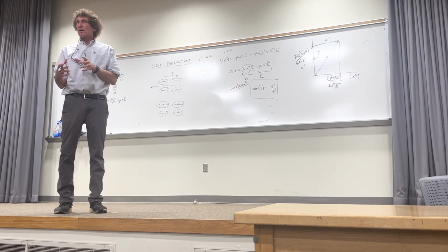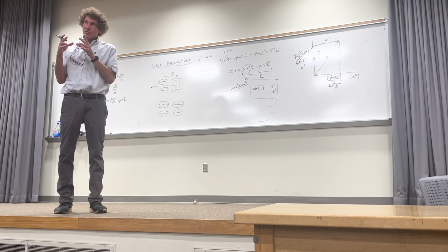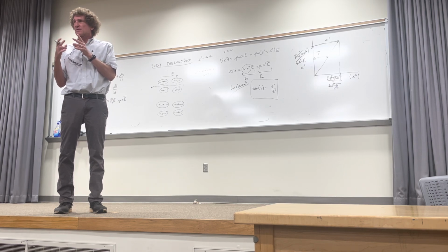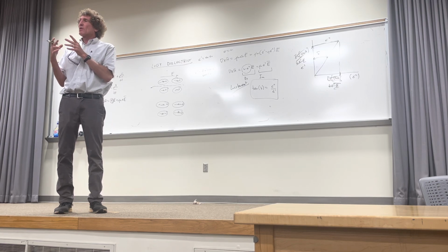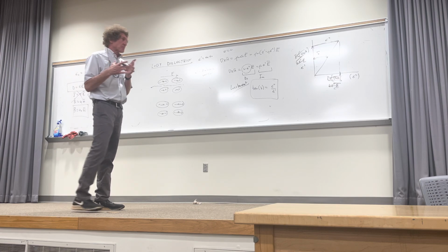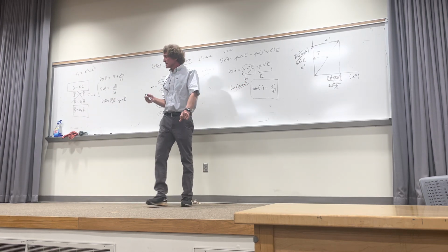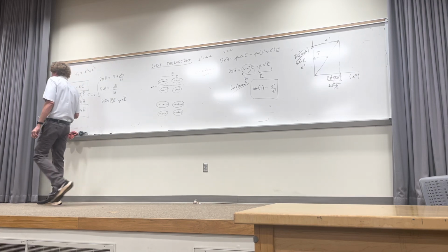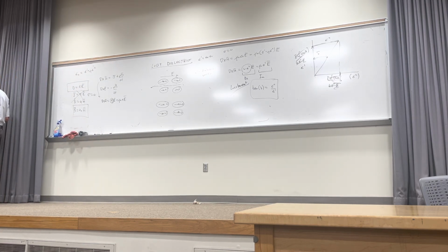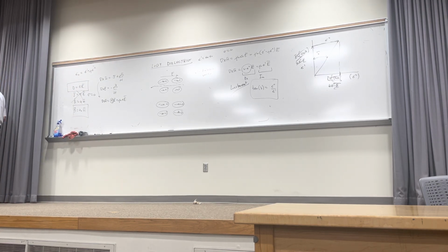Most of the time, they're not worrying about storing a lot of energy between these two. What they're concerned about is they want an epsilon relative that's greater than 2, 2.5, and they want something with very low loss at the frequencies of operation. And that's really what the loss tangent tells you. Now, in his book, I'm used to seeing tables and tables of given frequencies, but I'm just going to give you a reference to some.